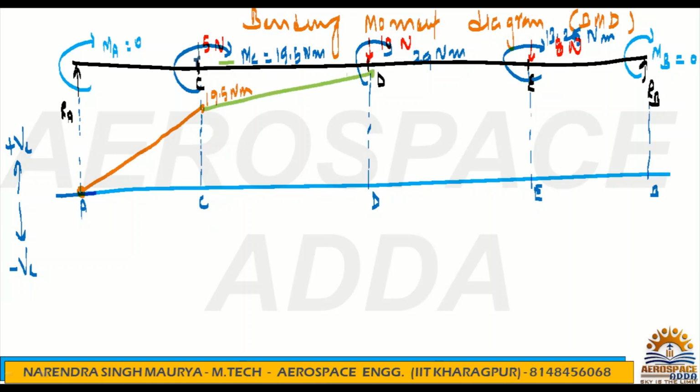Okay. This is now C, D, E, B you have reflected here. So see, this is C dash. This is D dash. Now come to point E. What is the moment at point E? 13.25, which is less than 29 Newton meter. So this E dash you can say somewhere here, because the magnitude is only 13.25, which is less than 29, so it will come somewhere here. Now this D dash and E dash you have to meet by an inclined line.